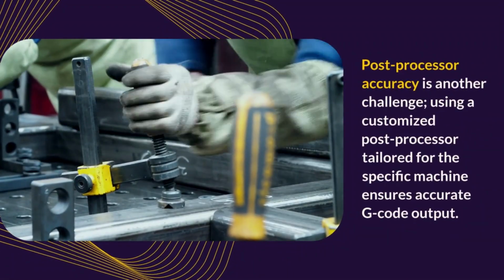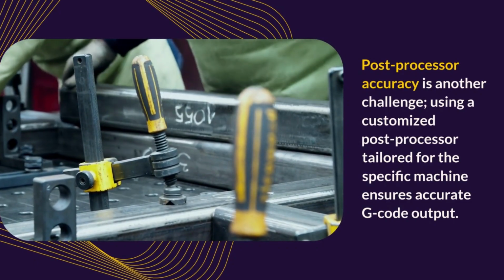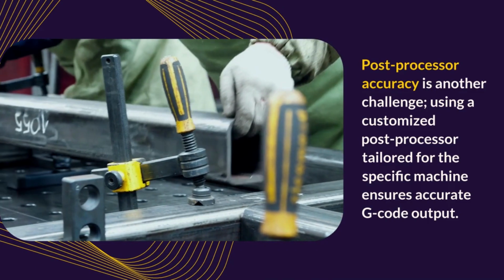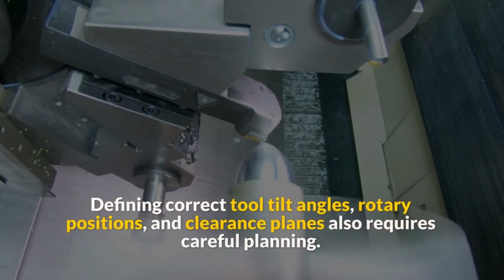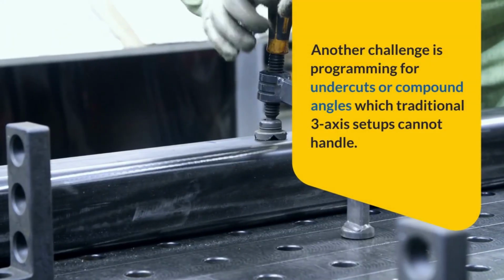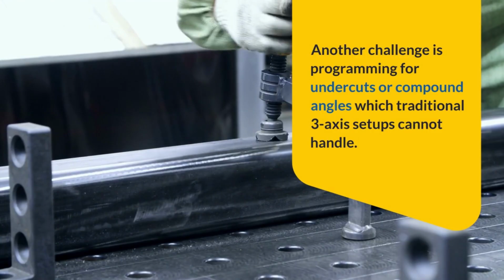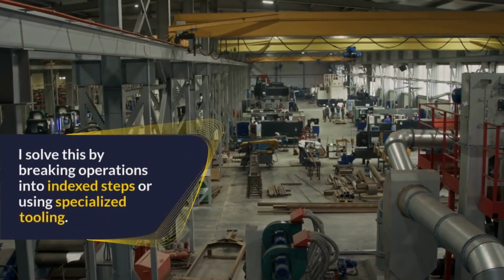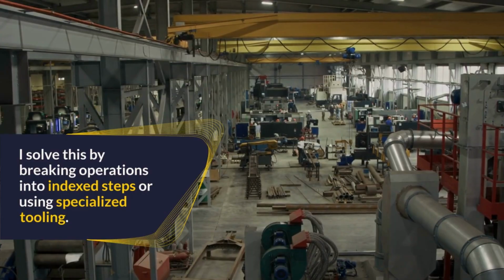Post-processor accuracy is another challenge. Using a customized post-processor tailored for the specific machine ensures accurate G-code output. Defining correct tool tilt angles, rotary positions, and clearance planes also requires careful planning. Another challenge is programming for undercuts or compound angles which traditional 3-axis setups cannot handle. I solve this by breaking operations into index steps or using specialized tooling.